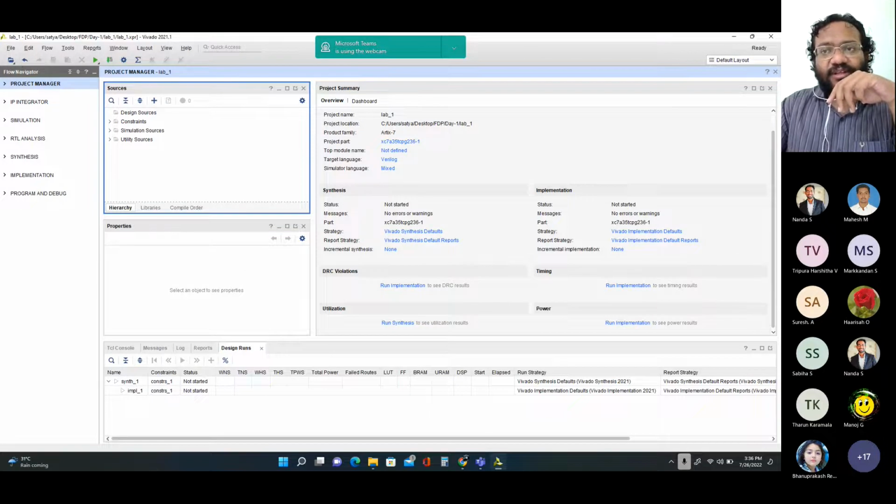So all those test benches which you are writing specifically to verify the functionality of your hardware design, all those files come under the simulation sources. These test benches are used to verify a module's functionality. So the simulation sources should also have a copy of the design sources folder. Then only will it be able to test it.